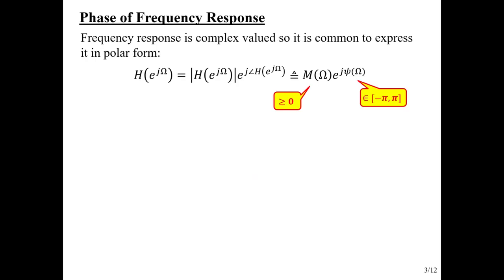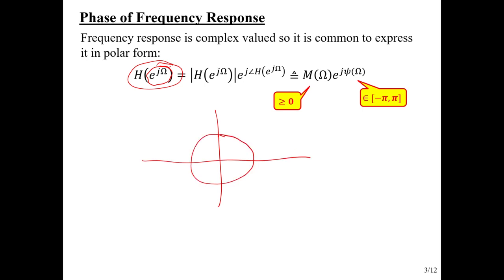Okay, so we've got the transfer function, and there's a couple different ways of expressing the frequency response. If you go back and look at my review notes for this course, you'll see that I use some other notation, but this is a common way. We're just taking that H of z and replacing it by e to the j omega so that we get a function of omega, but really it's just looking at the transfer function evaluated on the unit circle.